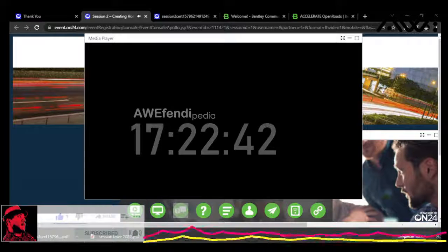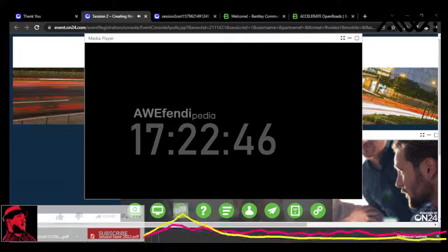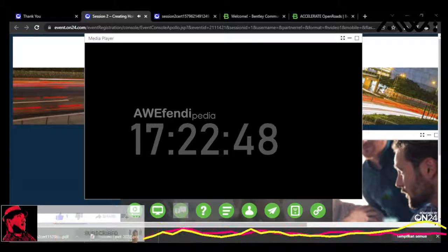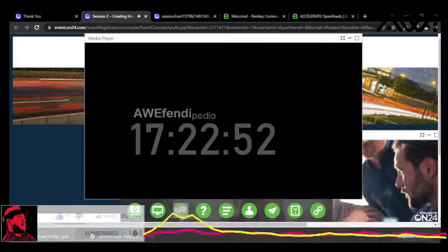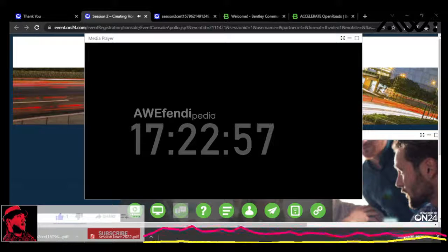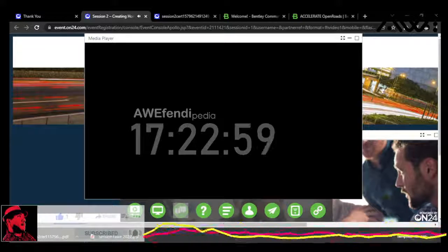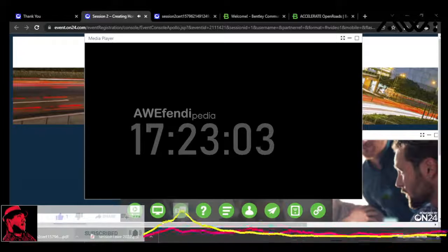Okay, now we're going to continue on. We're going to continue using geometric tools to place the curve in the next segment. So I'm going to go back up into the horizontal area. I'm going to pick arc from element, and I'm going to use this tool, simple arc from element. Now what this does, well, you'll see what it does. I'm going to follow the prompts. It's going to place an arc off of that initial tangent.